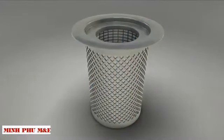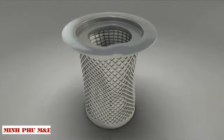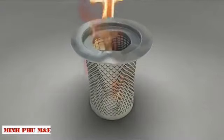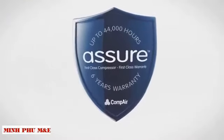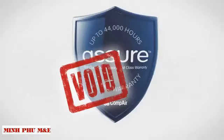In addition, there's the risk of a complete collapse of the air-oil separator due to increased pressure differential, or, if the element is unsuitably earthed, a fire caused by static discharge. And don't forget, if something does go wrong, you're effectively on your own. Using non-genuine parts voids your warranty.